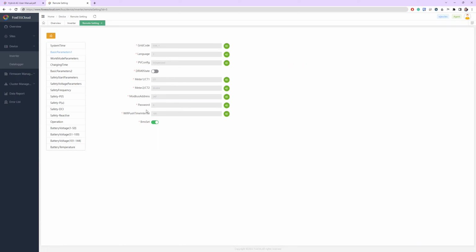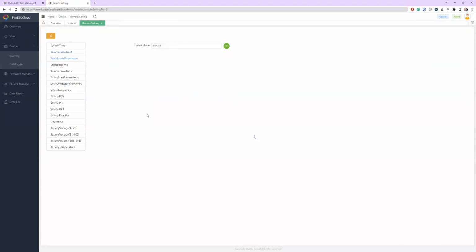So this option only applies to the solar hybrids, H1s. If you have solar but don't have batteries yet, you would not plug your BMS in, you would not turn it on, and you'd be able to mark this as disabled, and then that would avoid it having the error whilst you're using it just for solar. It's quite common while people are waiting for batteries to come into stock.